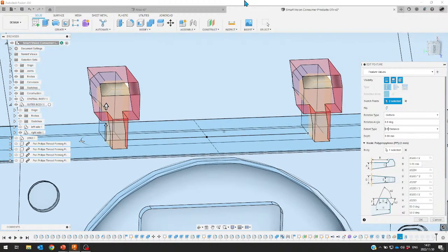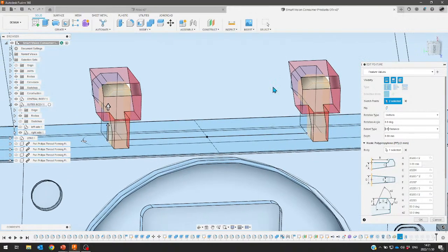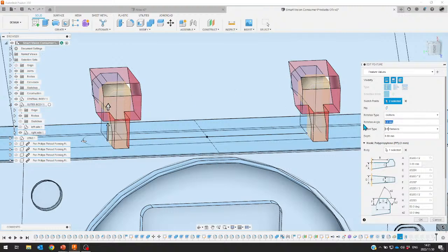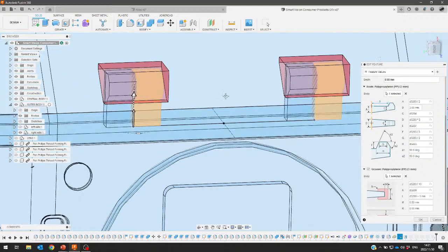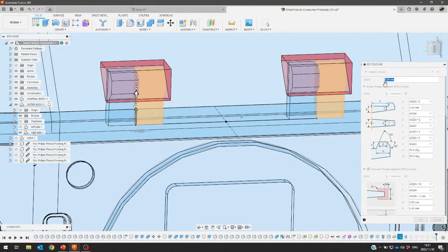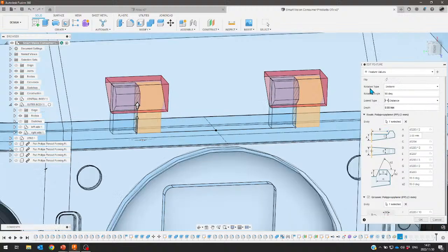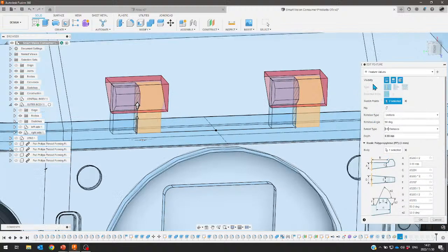So here in this case, we can see that the snaps are both essentially pointing to the left. I'm going to go ahead here and change the rotation angle for these to 90 degrees. We'll see the snaps will rotate to 90. So that will be a bit more functional for this part. And because we are editing the snaps, we cannot change the type.